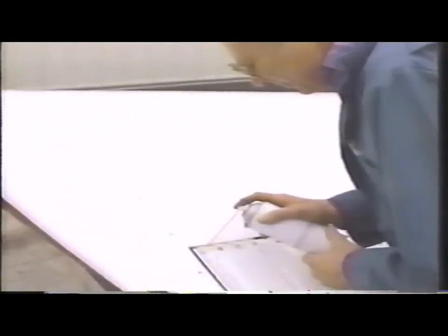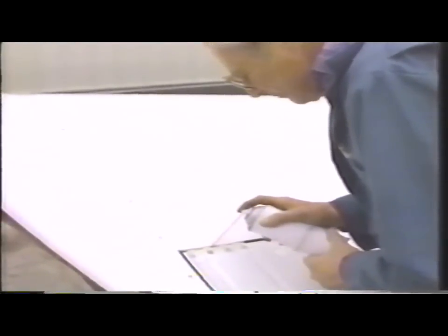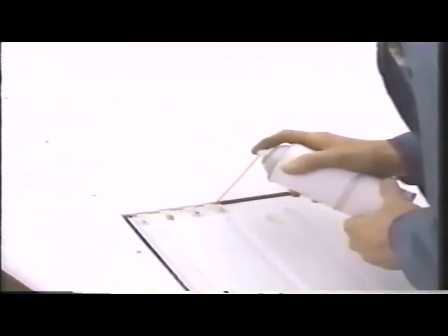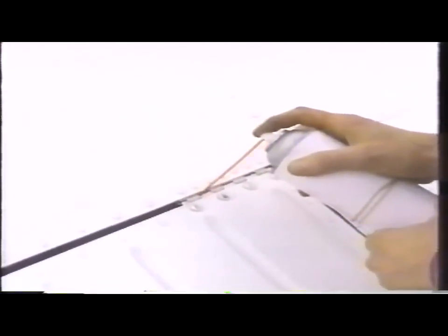Thorough lubrication and application of corrosion preventive compounds in conjunction with a detailed corrosion inspection should take place at least every 90 days. More inspections, as frequent as every 15 days, will be required in severe environments like those found near industrial or coastal areas.